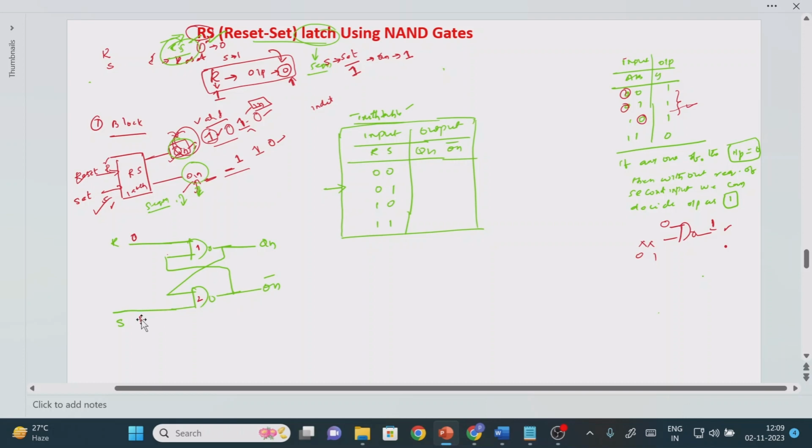The reason is that if the first input terminal value is 1, it is mandatory that you know the second input terminal value also. So for that reason we have explained this logic. Now for which logic gate can we directly find the output without knowing the second terminal value? Logic gate 1 or logic gate 2? The answer is logic gate 1. See that if one of the inputs equals 0, what is the output value? Output value equals 1. So for this Qn terminal we have obtained the output as 1.